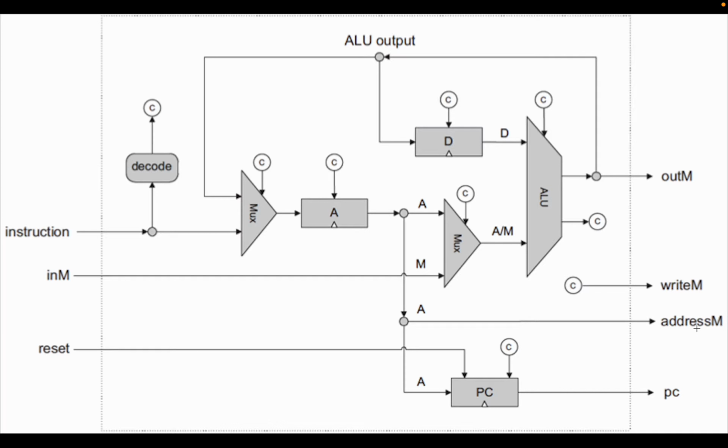So here is this code. The Not gate is used to tell that the instruction coming is an A instruction. The CPU decodes the 16-bit instruction into the opcode and the 15-bit value. If the opcode is 0, the instruction coming into the CPU is an A instruction. The CPU takes the 15-bit value and stores the value in the A register.